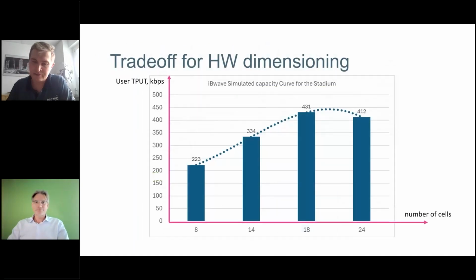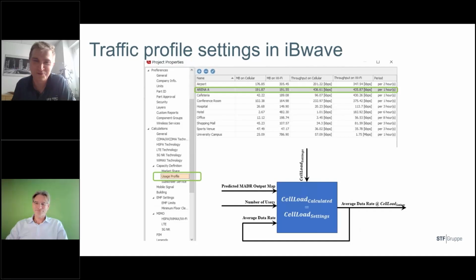Yeah, exactly. I think I will better repeat it. This character is more often seen for 1.8, 2.1, 2.6, these FR1 bands. For millimeter wave, this peak would be really hard to achieve. We can talk about it. But Ralph, as you mentioned in your slides, you have shown an augmented reality scenario, which is not the case nowadays in the stadium. But for augmented reality, I think you will need, as some people say, real 5G. Real 5G, this is millimeter wave, guys. So this is how we joke here.